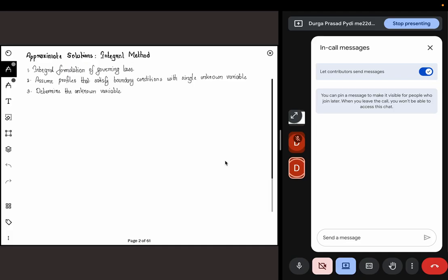First, we'll get started with the momentum integral equations. The idea behind this is that we have something called integral formulation. The previous derivations are differential in the sense that they are for a small control volume. Here we'll consider a bigger control volume, and we'll not worry about how things are varying inside in a continuous sense. We'll only be worried about the mean quantities, like we need the mean momentum to be conserved and the total energy to be conserved.